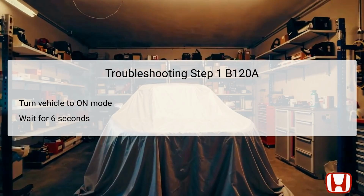The first step in troubleshooting DTC B120A involves setting the vehicle to the on mode. This means turning the ignition switch to the on position without starting the engine, allowing the onboard systems to boot. It is essential to wait for at least 6 seconds to ensure that all electronic components can properly initialize and establish communication.